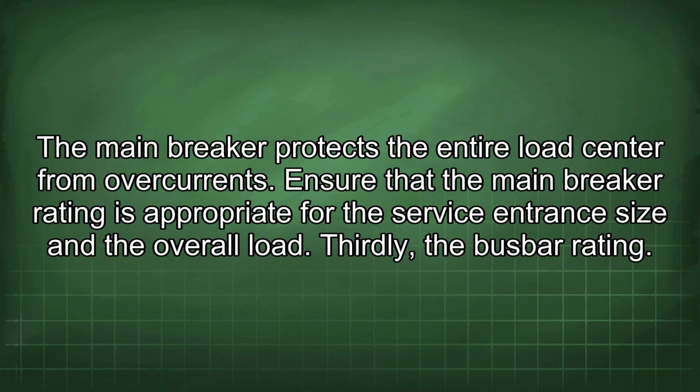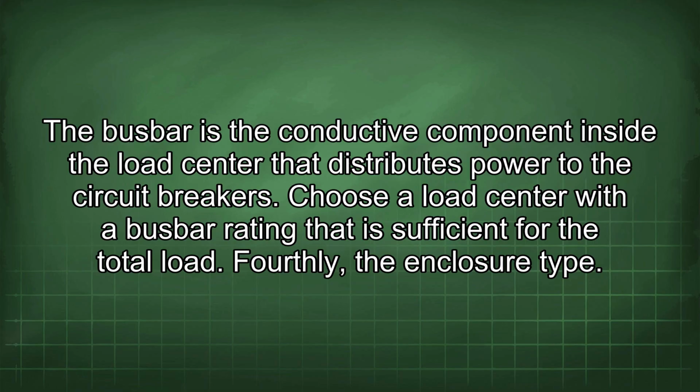Thirdly, the busbar rating. The busbar is the conductive component inside the load center that distributes power to the circuit breakers. Choose a load center with a busbar rating that is sufficient for the total load. Fourthly, the enclosure type.